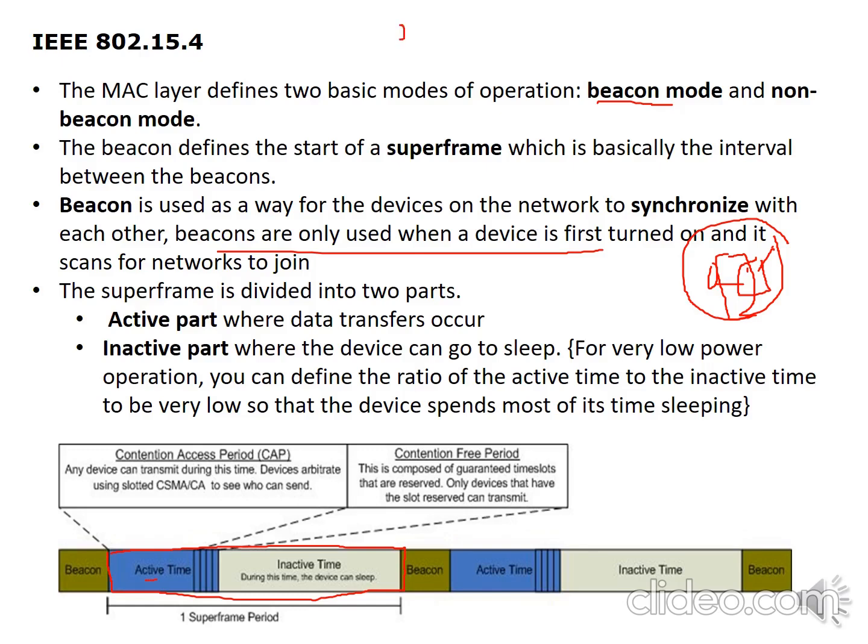You know that the end devices, or the router, or WSN nodes, have a limitation of power. So if those devices are active all the time, they will drain the battery in minutes. So to save the battery, we need not to keep them active all the time. They should only be active when they want to send some data.